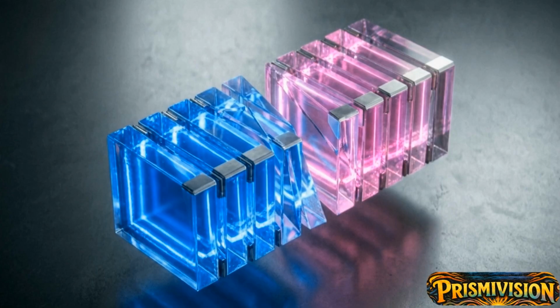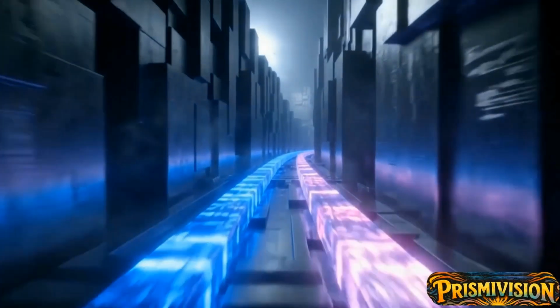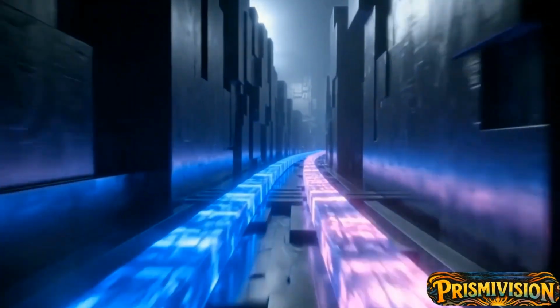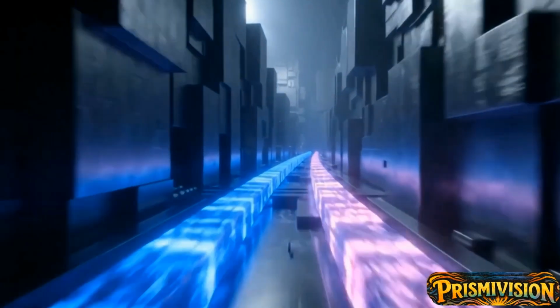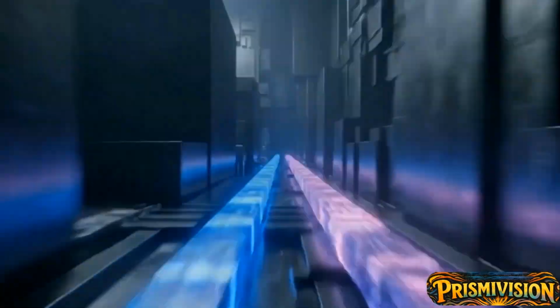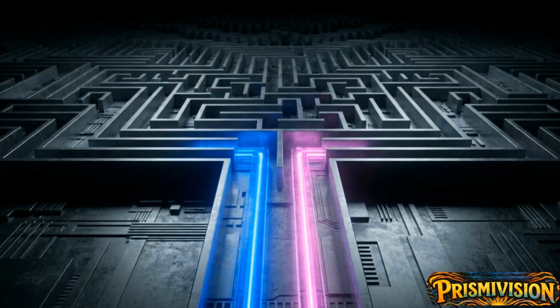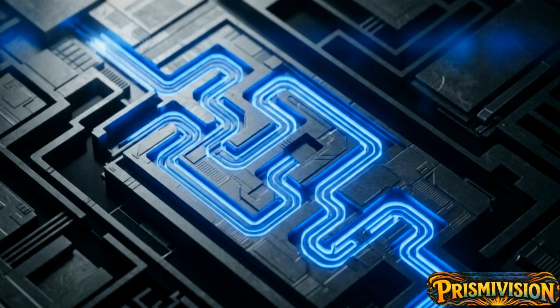The moment it arrives, that 32-bit package splits. It sends distinct electrical signals racing to both the register file, where data is stored, and the immediate generator at the exact same time. The instruction is now inside the processor, but it is raw data. Before math can happen, the chip has to physically route these signals through the correct channels.